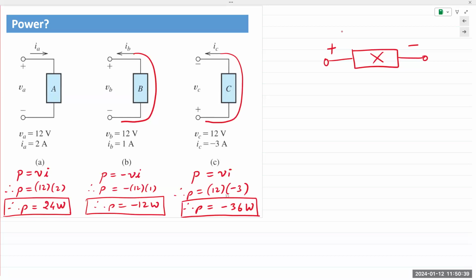This is an assumption that I am making in order to solve this problem. Then logically, remember I said the assumptions are made in certain logic. Once I assume a voltage polarity, if I know that the element is not a source, the current goes from plus to minus. Do not worry about electron charges or hole charges. Positive charges, negative charges, we're not worrying about charges at all. Again, we are not going into physics. We are not going into semiconductor device physics. We are simply looking at electrical current, not at electrical charges.